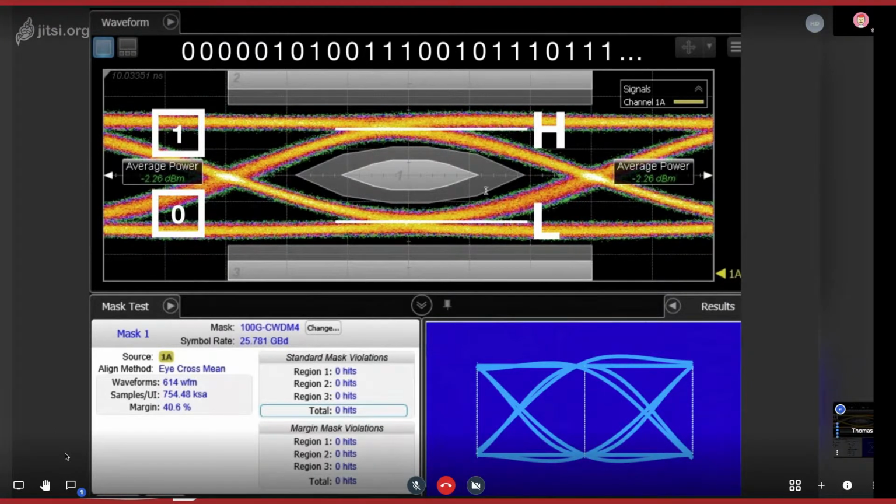So it's really important to determine for a receiver that the eye is clearly opened and does not cross that shape in the middle. So this shape is really important to make an eye diagram. As I said, a 100 gigabit transceiver measured with a speed of 25 gigabaud.